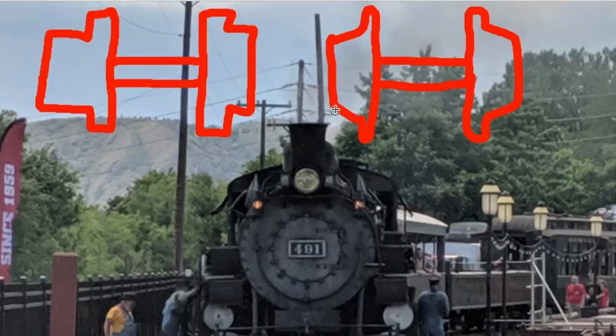But it also means that if the rails are a little further out, you just ride a little further out on the taper and the locomotive sits down a little bit more. Or if it's a little bit narrow, it rides a little bit closer, which provides a problem as well. But you've got a couple inches here of play in these wheels, but obviously that gets extrapolated with how fast you may be operating your trains. So the faster you run, the tighter the tolerance has to be.